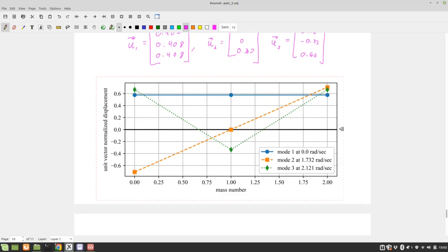Your second mode at 1.72 radians per second are your wings tipping. And then your third mode is kind of the V shape, right? Honestly, not having done this problem, I could have told you the first mode, because that's easy. I would not have known 2 and 3. I knew those would be the first two modes, but couldn't tell you which one happened first. And you could adjust those if you were really worried about what your modes are.